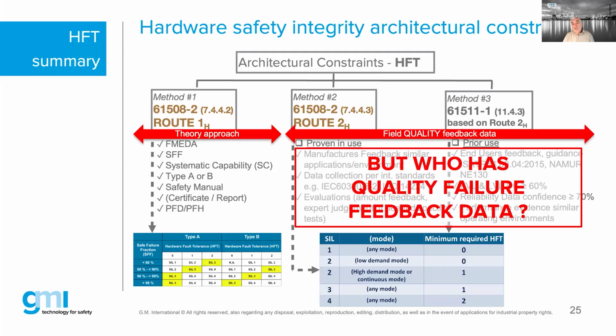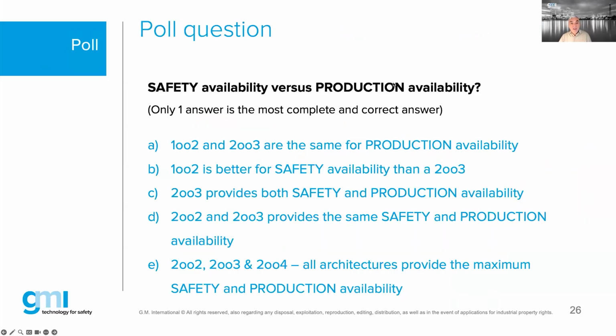Who of you is not using simply a database that you either found online, or maybe asked ChatGPT, or maybe you bought a commercial database with some average generic failure data and you whack this into your calculation tool and you believe that you produce a verification report or a self-verification that is actually stating how available your safety system is. In other words, not many clients today have very good failure records or failure data. There are some, but they are very rare to find in the industry.